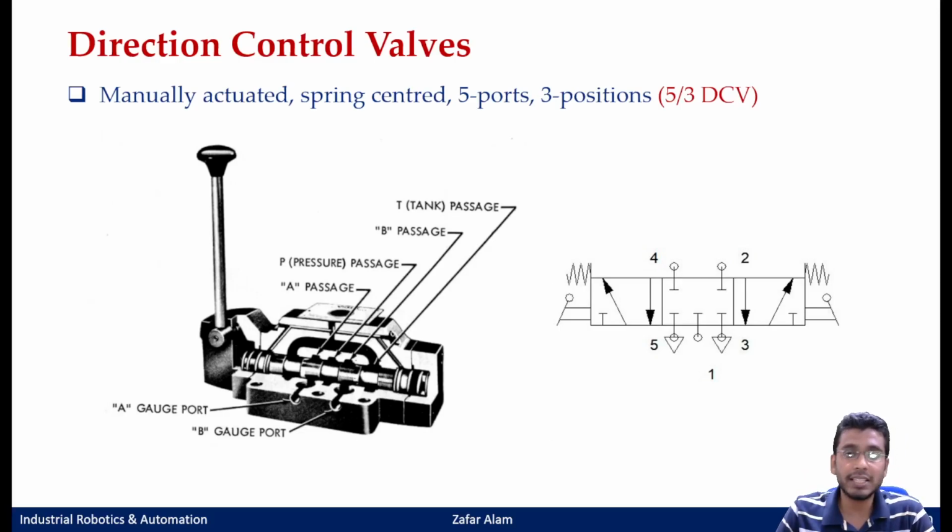Okay, it is spring centered. How is it spring centered? See, these are the symbols of a spring centered valve. That means your default position, since the numbering is on the center position, 1 2 3 4 5, whatever is the numbering of this valve. If you see, I have only numbered the central position of the valve. That means my default position of the valve is the central position.